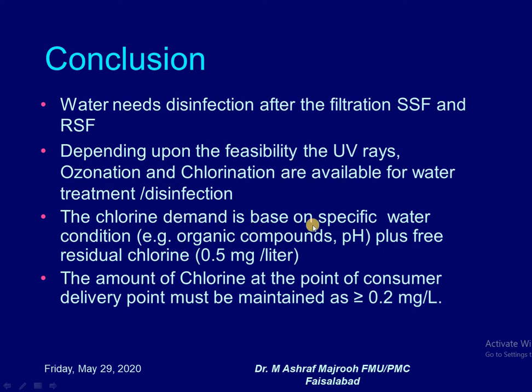The chlorine demand is based on the specific water conditions, organic compounds and pH, plus free residual chlorine of 0.5 milligram per liter is required. The amount of chlorine at the consumer delivery point must be maintained at 0.2 milligram per liter.